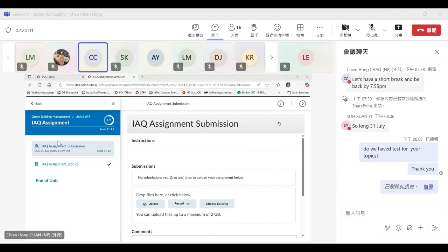That's what we are always facing in our building. Very common. Another case, when I last worked in a shopping mall, was mostly the pipes. Pipes will cause foul smell and bad air quality, and the ceiling condensation is also because of the chilled water pipe, causing all this moldiness and smell. Of course, another source is actually pests, in some offices because of the way some colleagues keep their food or their personal items.